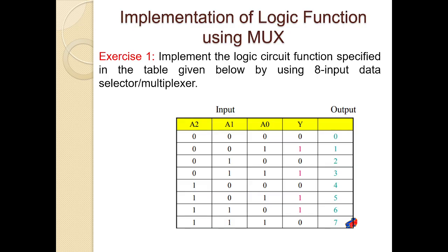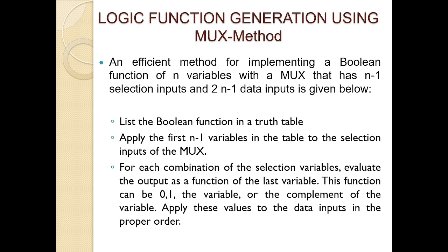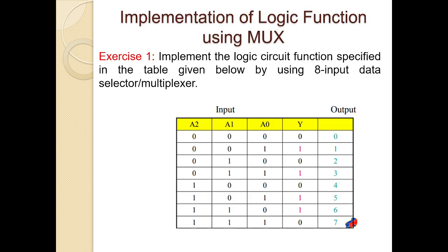The implementation of logic functions using a multiplexer. Exercise 1 is to implement the logic function specified in the table given below by using an 8 input data selector or multiplexer. This is one exercise problem. Try it and draw the logic diagram of the multiplexer like we designed the 8:1 multiplexer.